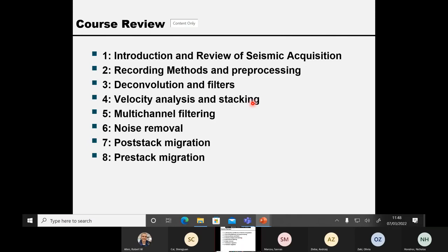3 things I think I should emphasize. A, we learned a very quick way to derive a discrete Fourier transform based on Z transform, right? So Z transform is a polynomial. For each term, the coefficient is the amplitude of the sample, and the power of that is the index of time, right? That's very straightforward, Z transform. This Z transform is very important for the whole course here. I just give you examples, right?